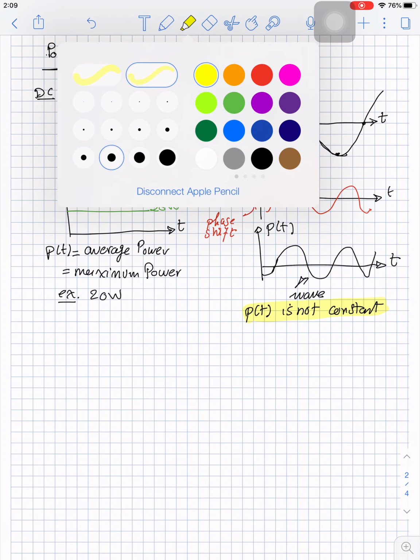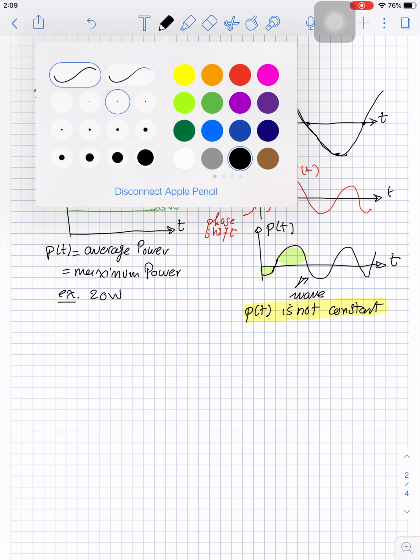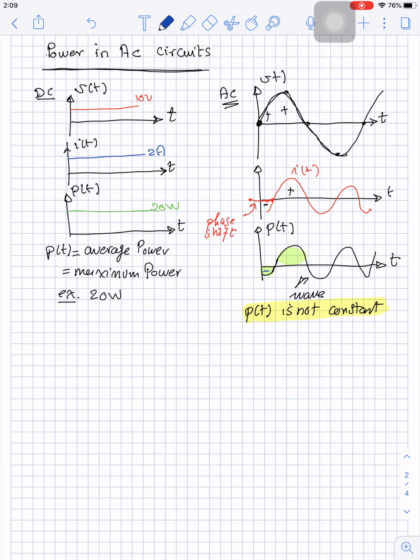And you can see here some interesting part. So this part here, the first part, it is negative, which means your power is negative. And I'm assuming load notation here. This means you are giving power back. Or when your power is positive, you are consuming power. So here the power between the source and the load is interactive.